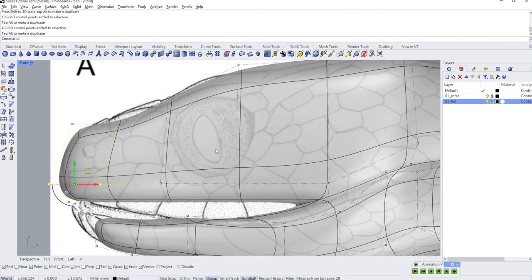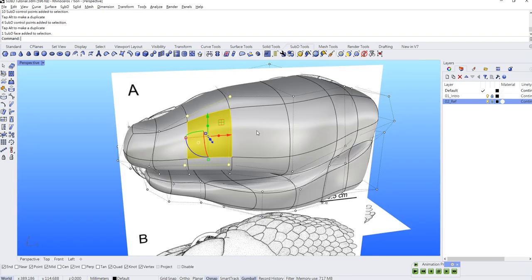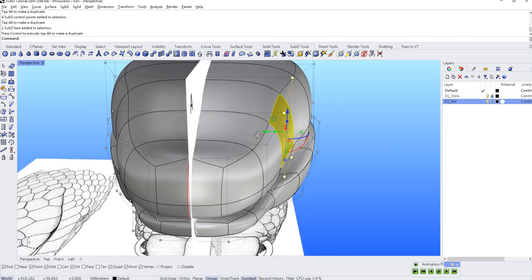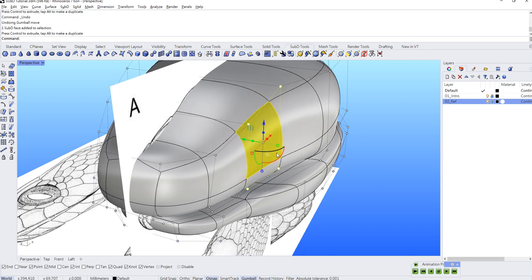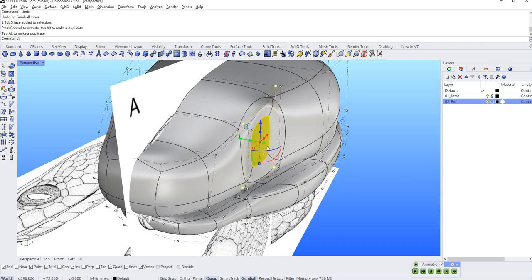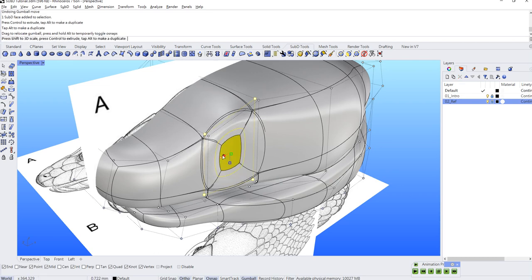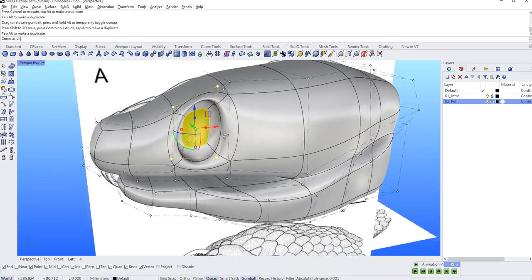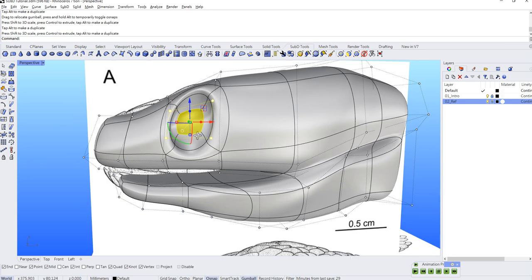Okay, so let's select the face right here. Hold on your Shift and Control key, go to perspective view. Now I'm going to extrude the eyeball. I'm going to create the eye holes for putting the eyes. So let's select this one and let's scale down a little bit. Hold on your Shift key to scale down. Extrude again so that you can create a hole inside. And probably the shape is not correct, but we can adjust the geometries.